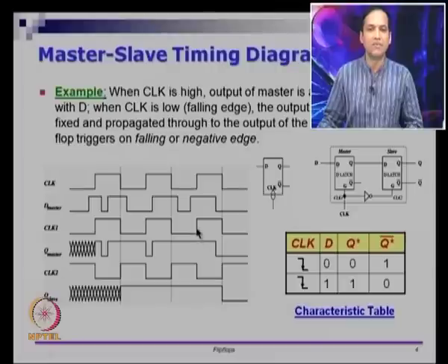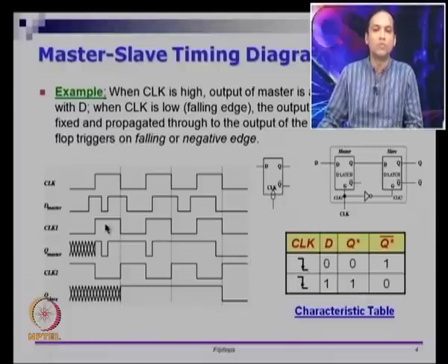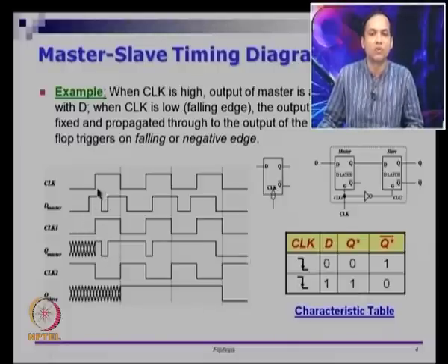And finally, when the third clock tick comes on, at that point D master is already 1, it goes down to 0 once, and that is captured in Q master, right. So if you notice, what we have just traced is the relationship between the external clock, D master and Q master. If you compare D master and Q master, you can see that not all the transitions in D master are transferred to Q master, right. So a subset of the transitions are actually left out.